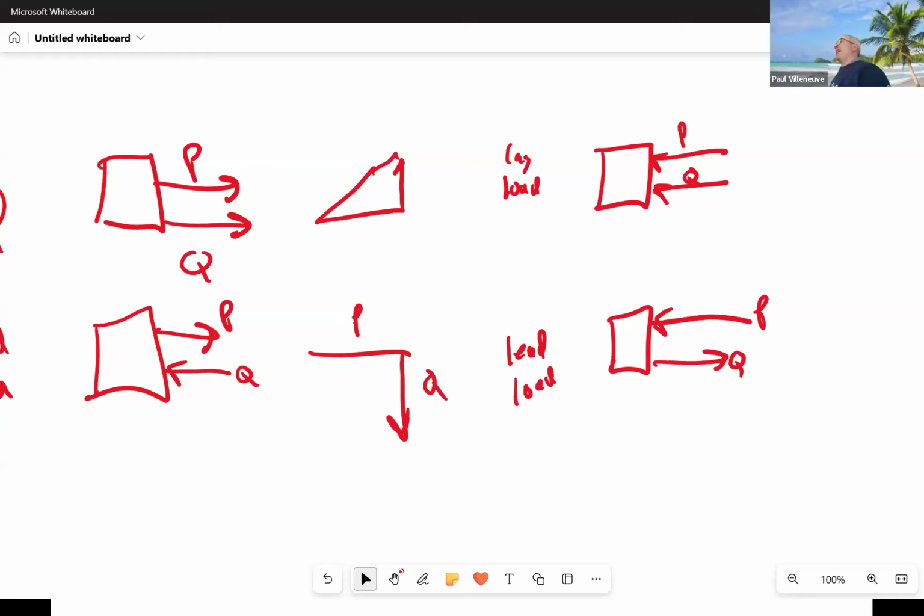And sometimes you need to do that. At night, when the transmission system is pretty lightly loaded, your voltages tend to be really high and your current tends to be pretty low. Well, because you've got basically big capacitors, right? If you think of wires and they're energized, then they are basically large capacitors. So the overhead system at night can put out a lot of reactive power. And so then you have to operate the grid at a lagging, or the generation in a lagging power factor mode. That's why the inverters, remember I said they can operate in leading and lagging power factors? Because the grid demands it.